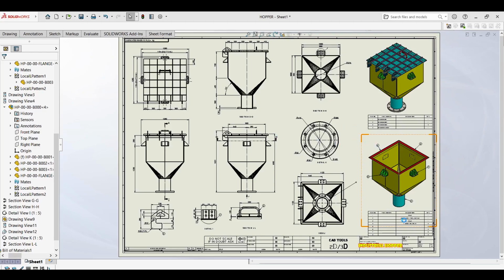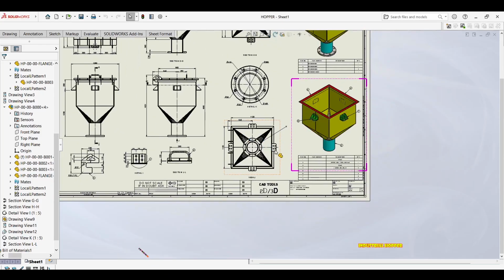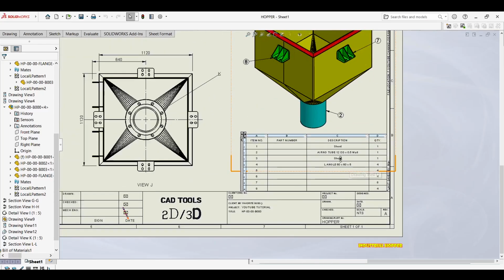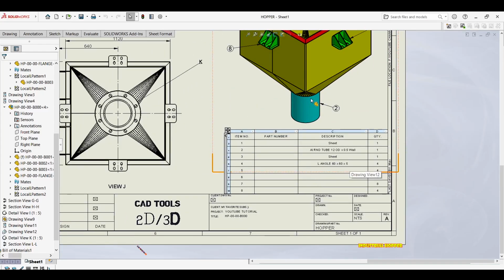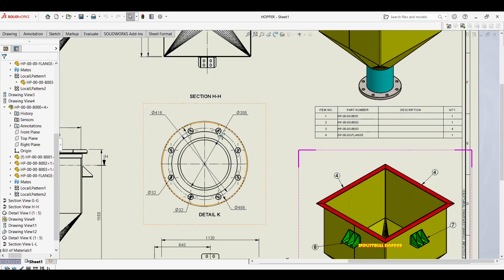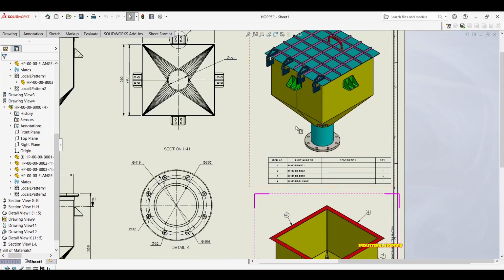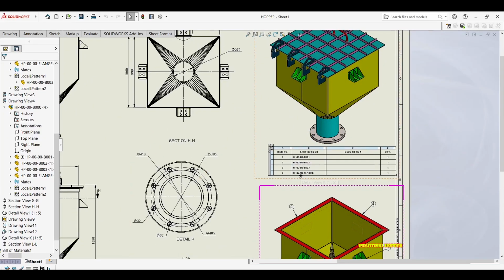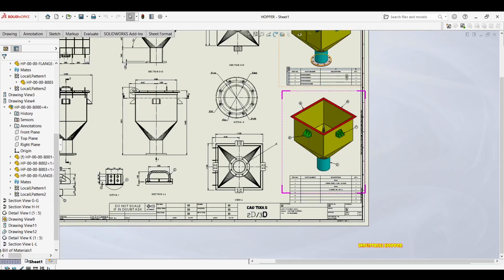If you want to edit the parts in here, you can just edit the parts and make sure that, like I showed you on the other tutorial, the long tutorial on the structures, if you want to edit the names, you do it. For this one, you're gonna do it as a multi-body part in that cut list way, and then this one is the description that you put in your assembly, which is different.